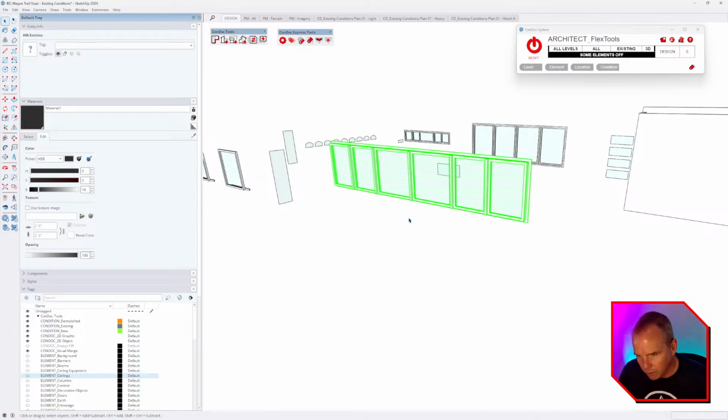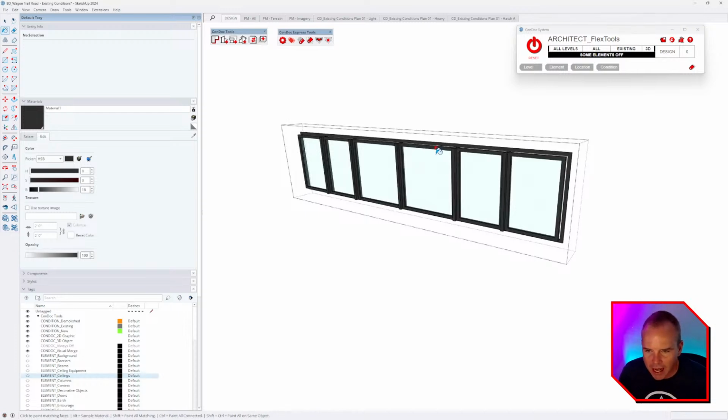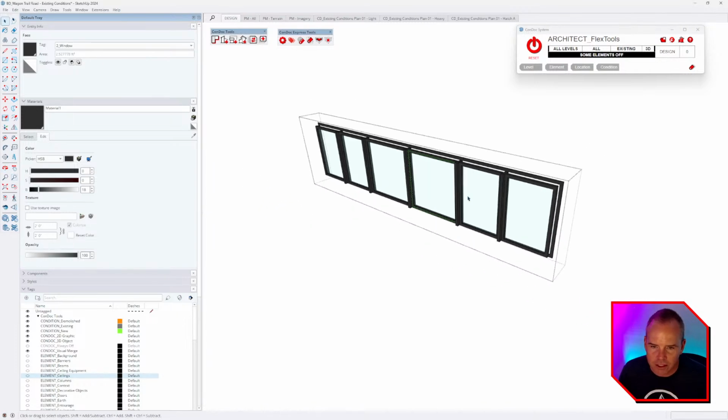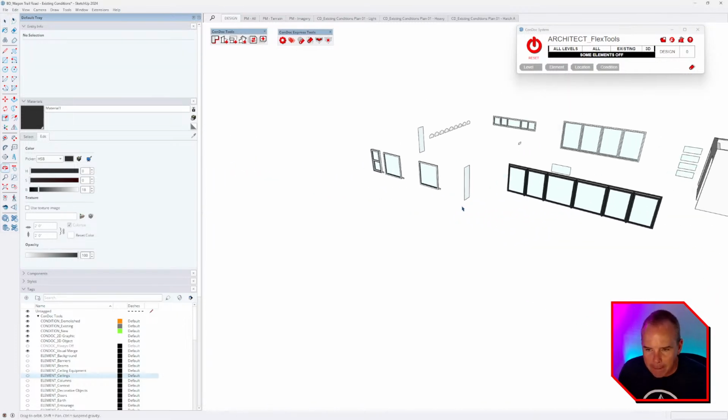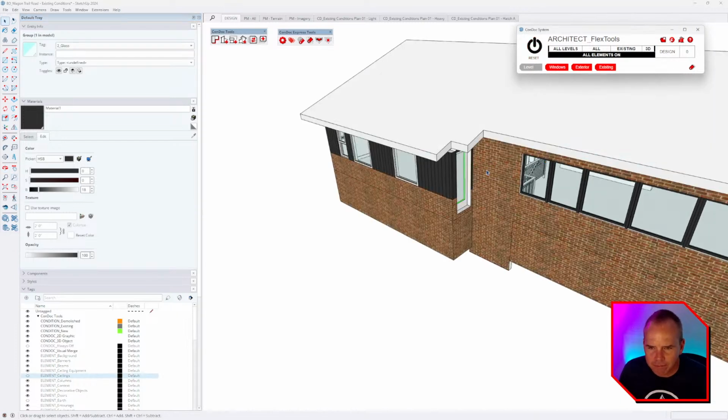But now I'm going to group this, and then I can double click in, and with my paint bucket tool tap shift and then just click one time, and now I've assigned the material to the surface. All right, so that's kind of like best practices there. Let me hit reset.